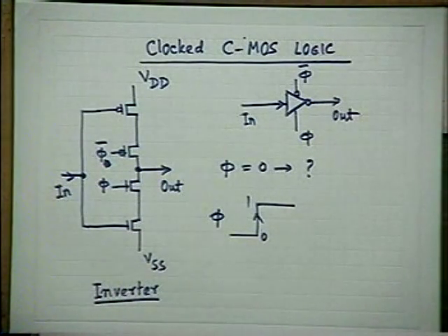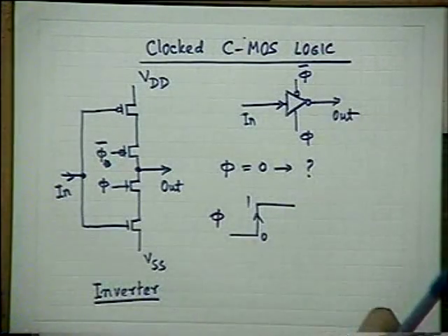So this is nothing but clocked logic. This is the same thing, but the clocked version. Whatever functions we could do with static logic, you can do in the same way with this one. The only thing is that here you are permitting the output to go in the proper format only when the clock goes high, not during the period when the clock is low. Okay. Now, in this case, what is the advantage and what is the disadvantage?